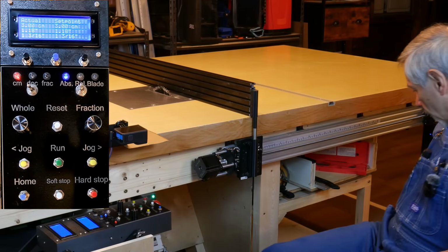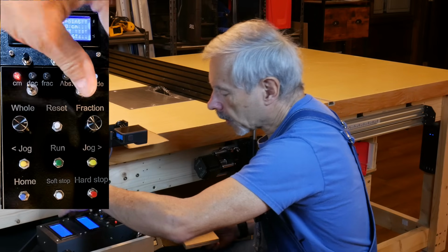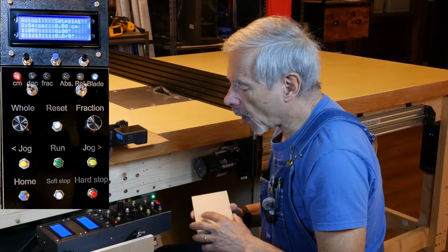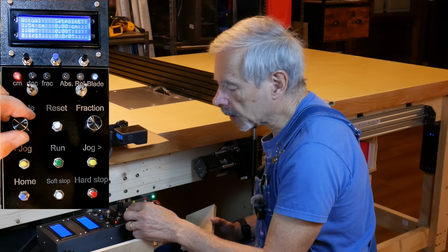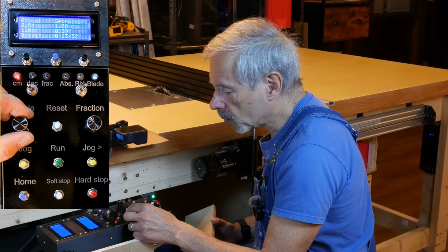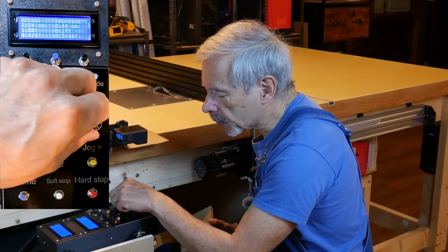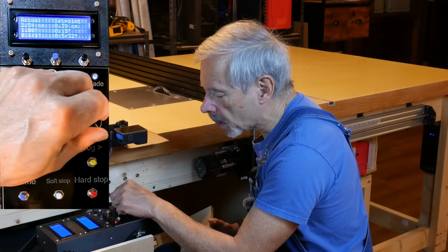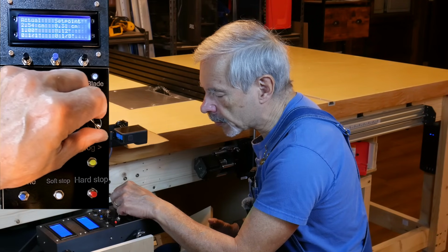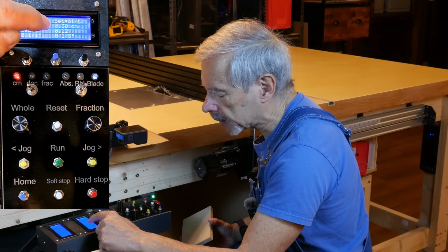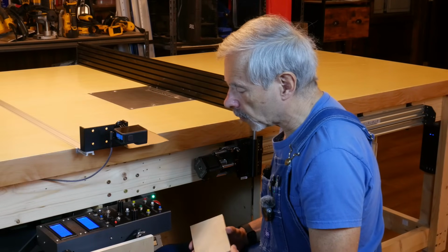Okay, there was that. And I had prepared a few boards of wood. In order to show you how a dado can be cut, I'll reduce the blade height to something more modest, like let's say 3 millimeters. For that we watch this display here. The display is in centimeters, so 3 millimeters are 0.3 centimeters, just like I set it now. And here the blade is moving.